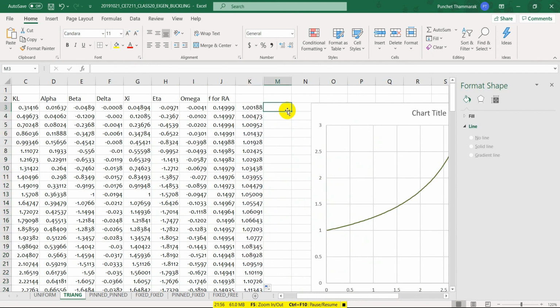Now you find the R, you find the M already. You can take moment on the other side. If you take moment, you have reactions multiplied by length. The reaction is given already in this column. You have the moment at the starting end already. You will have the triangular load, which is W times L square over 6.